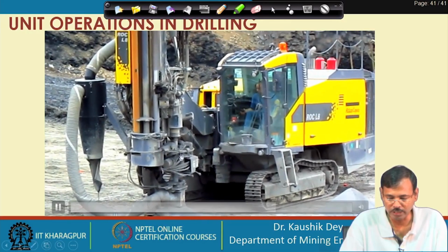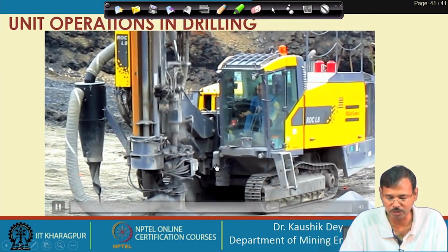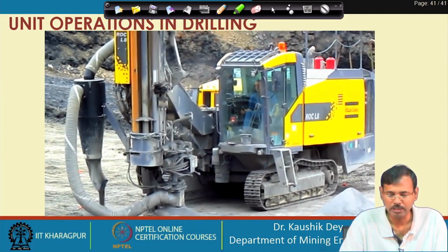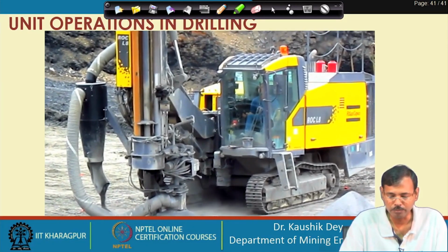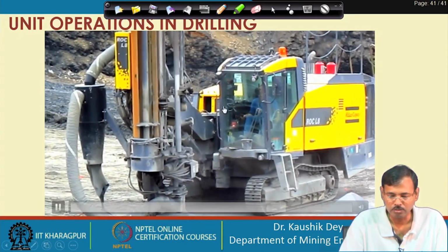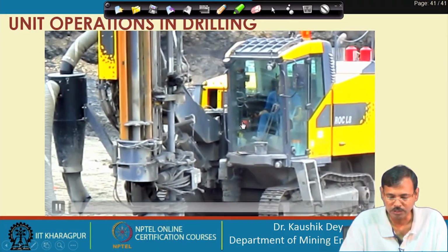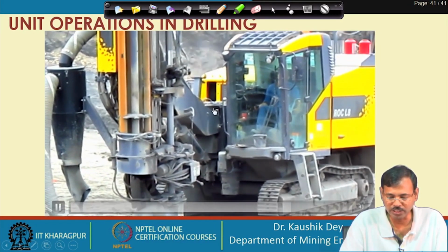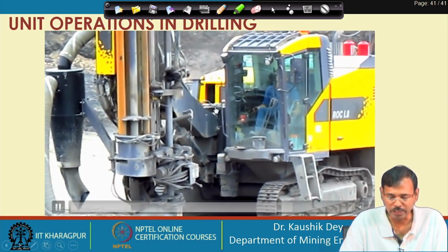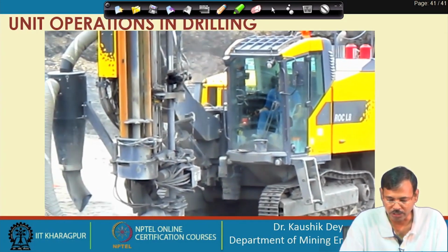Now, they are untying the shank adapter from the drill rod. See, the shank adapter now is being untied and it is taken up. Now, automatically the second rod will be inserted. Now, the shank adapter is this, automatically the second rod is placed. First the shank adapter is being tied with the second rod, then the shank adapter will rotate this second rod.